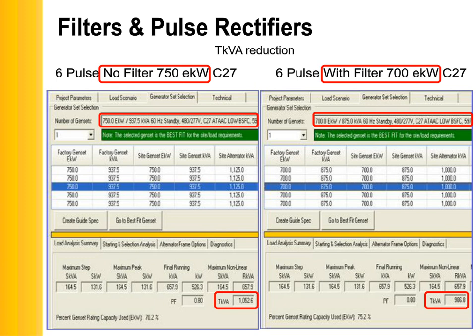Those two things are: you can add a filter, evaluating whether you can add a filter to a nonlinear load, and you can also increase the pulse rectifier. We've got a range of pulse rectifier on most nonlinear loads from 6 to 24. With the UPS load, we've also got something called IGBT. But remember, the higher you get on your pulse rectifier, the closer you get to a linear load, and the more you mitigate and reduce those harmful effects of harmonics and distortion.